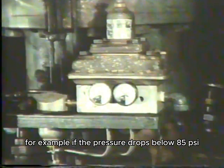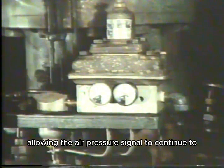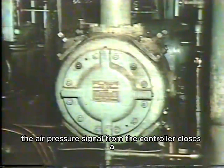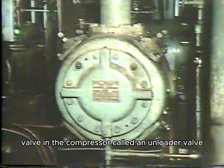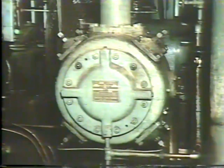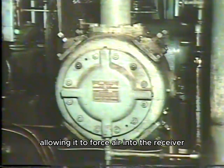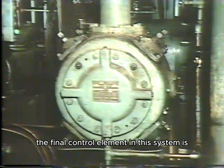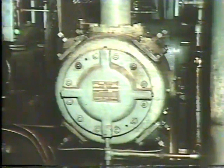For example, if the pressure drops below 85 psi, the instrument opens a valve, allowing the air pressure signal to continue to the final control element. The air pressure signal from the controller closes a valve in the compressor called an unloader valve, allowing it to force air into the receiver. The final control element in this system is the valve in the compressor.